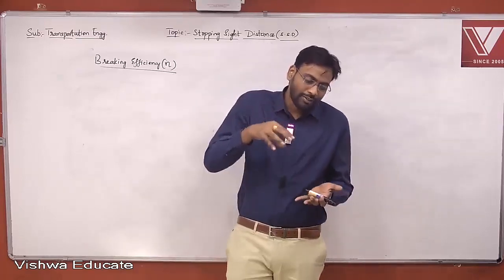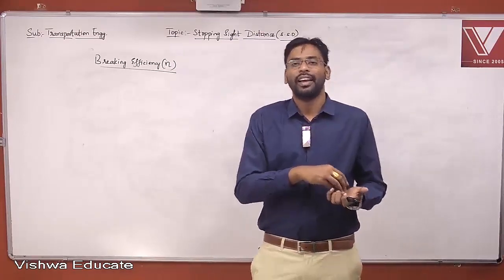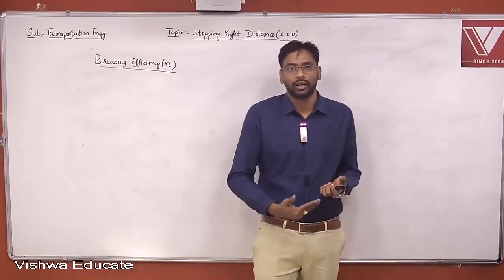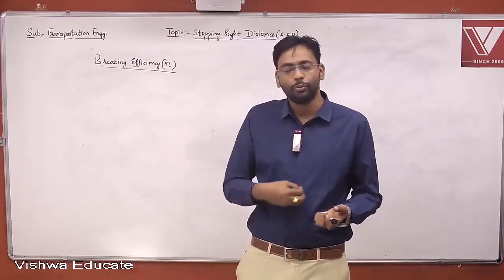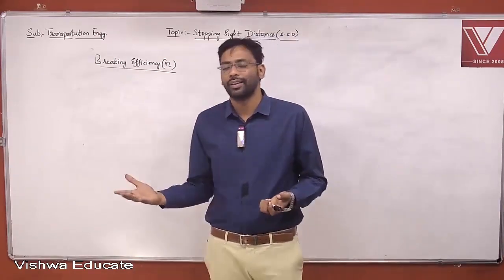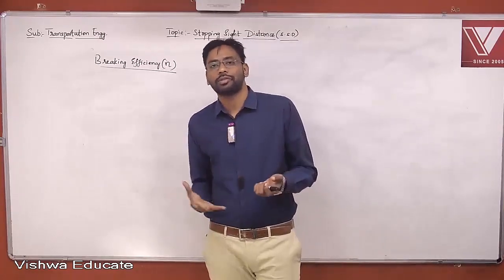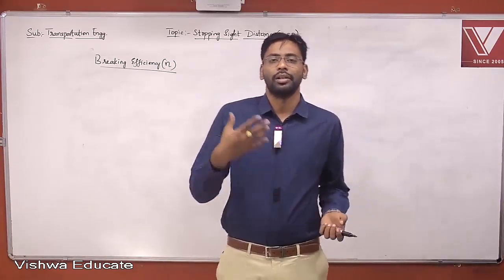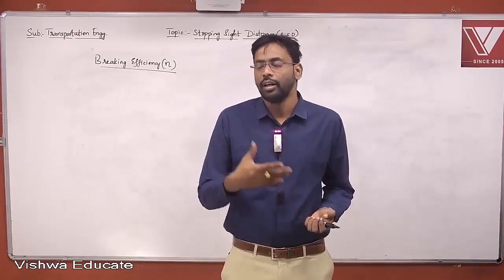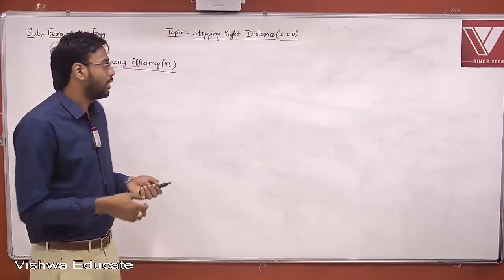If the vehicle stops there itself, that will cause skidding and even an accident. So we won't generally maintain an efficiency of 100%. Our brakes will not be that highly efficient. Generally we maintain 70 to 80%, and you should frequently go for brake tightening.